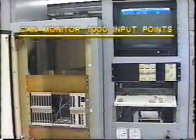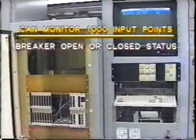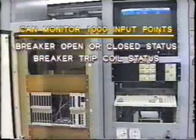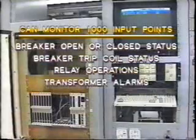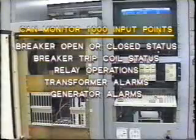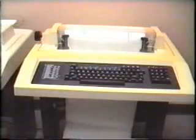This type of recorder is capable of monitoring 1,000 input points. For example, breaker open or closed status, breaker trip coil status, relay operations, transformer and generator alarms, and so on. The SER is constantly monitoring the status of each input point and prints out a detailed record whenever the status changes.